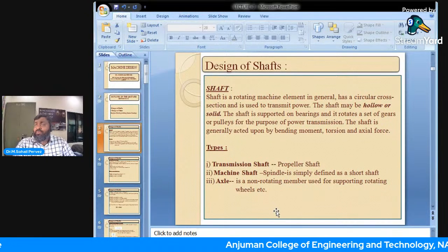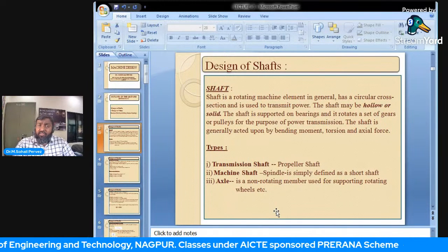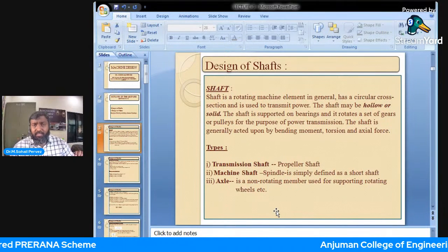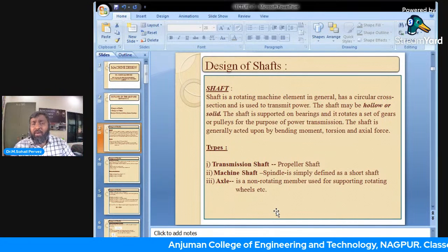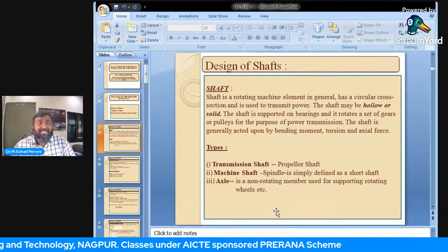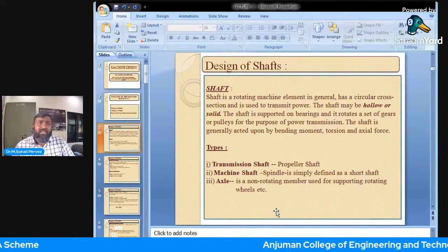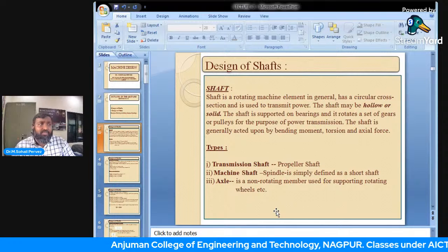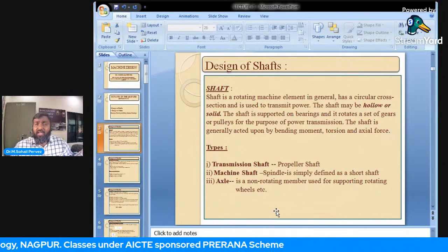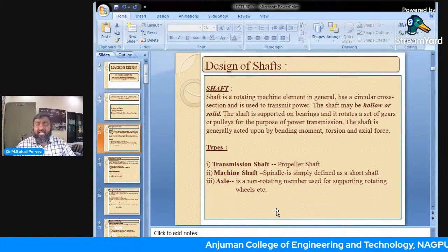Now, generally axles are of two types, live axle and dead axle. If it is live, definitely it will rotate. But if it is a dead axle, in that case, its shape may not be circular, but it will help to transmit torque or power or circular motion through its existence or through its fabric. It means that it helps in transmitting power, although it is not itself transmitting power. The best example is in a heavy commercial vehicle, the front axle. Generally, an I-beam section is there. It is not rotating, but through the kingpin and the arrangement, the axle is allowing the wheels to rotate. That's why it is a dead axle.